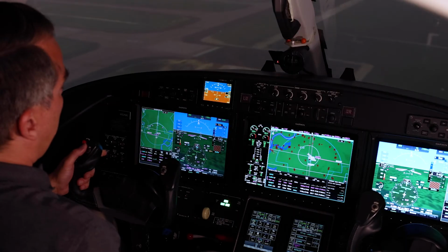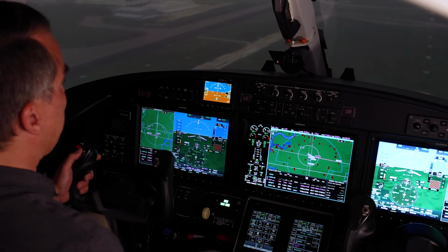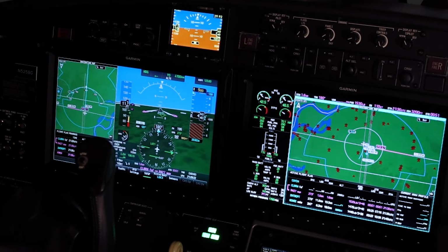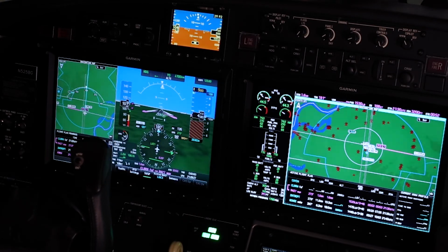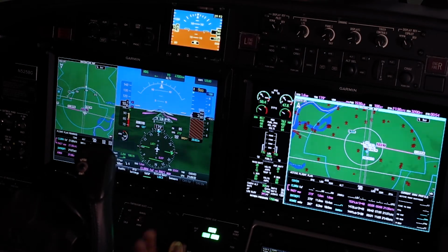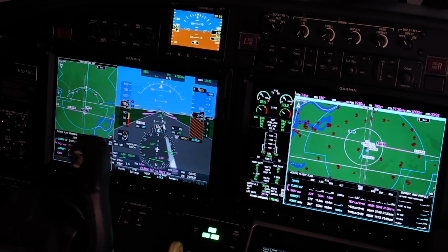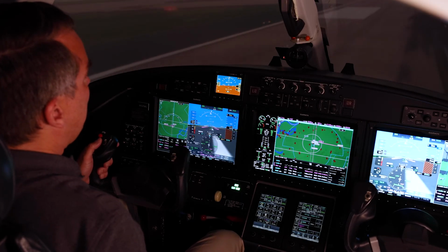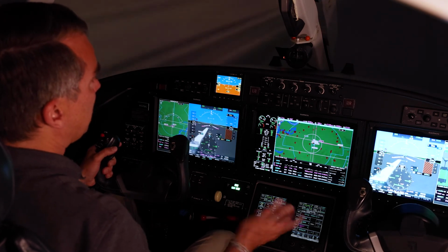And a good circle to land doesn't need to feel rushed. You should be able to maneuver, especially with that expanded circling area, so that you have plenty of time to get wings level on final, make small corrections as necessary. I can see on my synthetic vision, I'm on more or less a perfect 3-degree angle, even though I don't have a PAPI or a VASI. So I know my angle to the runway is good. My final gear and flap check, I'm basically right on my ref speed. Bring the throttles to idle. And again, there's no reason that this should be any more challenging to make my touchdown point and speed than any other landing.